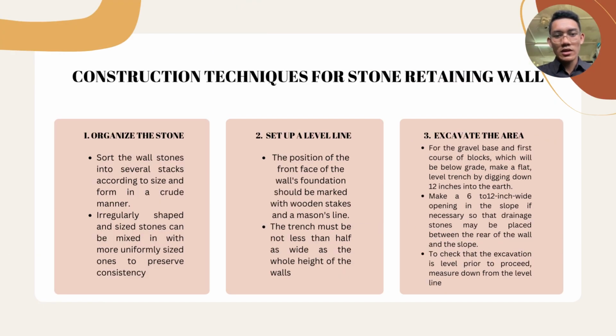These are the construction techniques for a stone retaining wall. Number 1 is organize the stone. Sort the wall stones into several stacks according to size and form in a crude manner. Irregularly shaped and sized stones can be mixed in with more uniformly sized ones to preserve consistency.